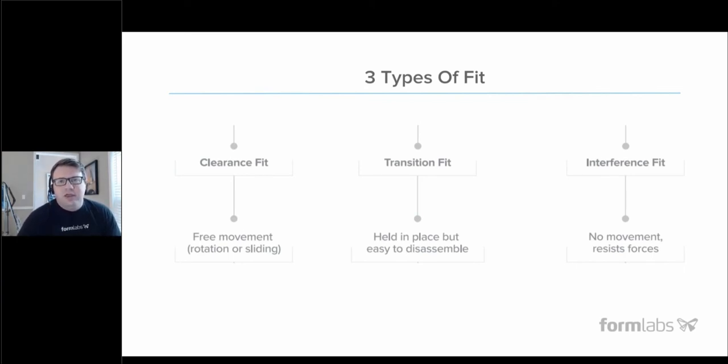A transition fit, this would be kind of like a peg and a pegboard where it takes a bit of force to push the peg into the hole, and that is enough force to actually hold that peg in that hole, and you can still disassemble that part relatively easily.